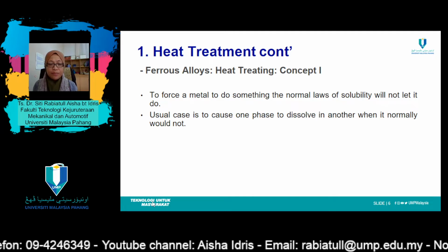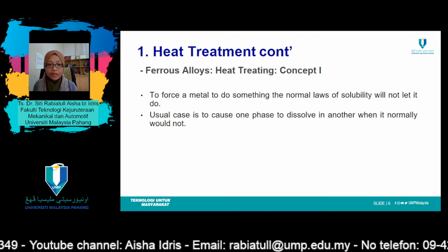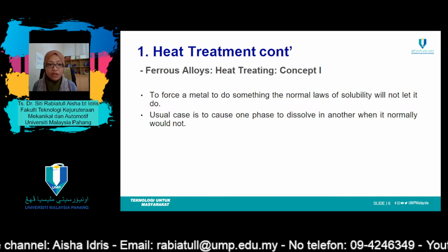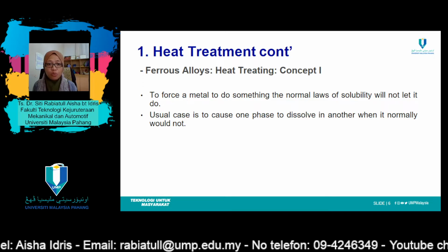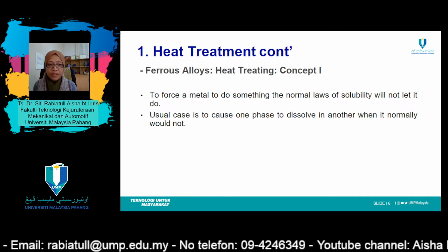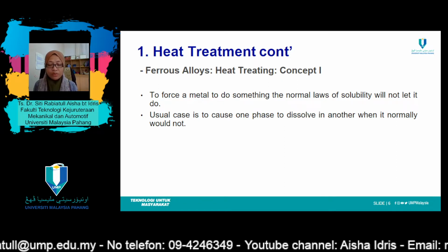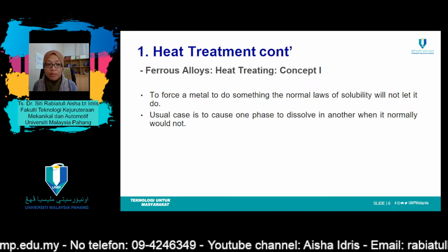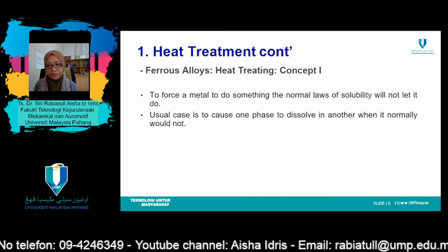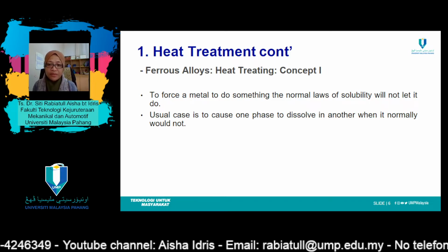is actually a process of heating the metal without letting it reach its molten condition or melting stage, and then cooling the metal in a controlled way to select desired mechanical properties. Heat treatment is used to make a metal stronger or more malleable, more resistant to abrasion, or more ductile. So if you look at the concept for heat treating the ferrous